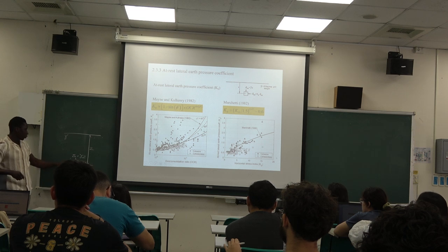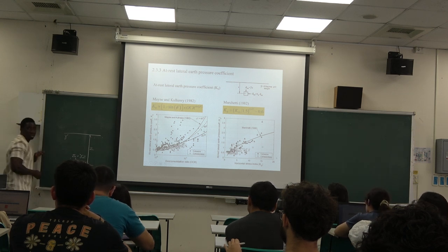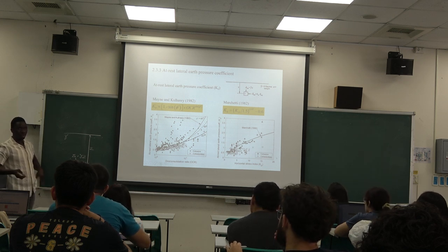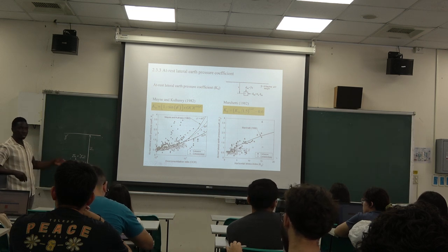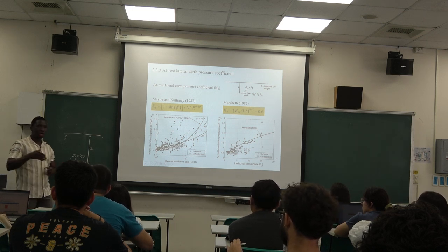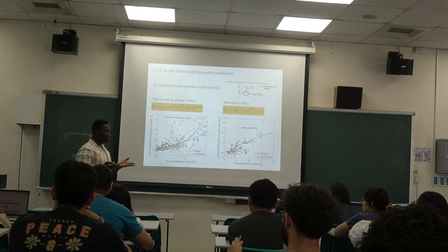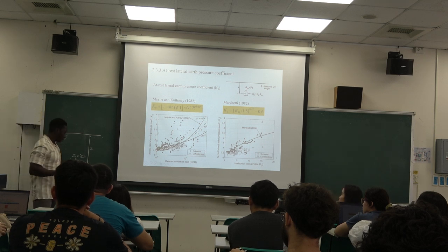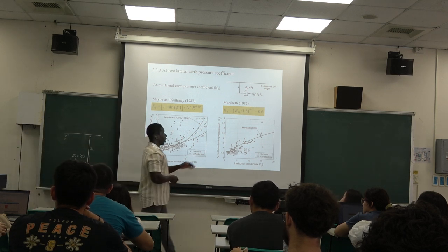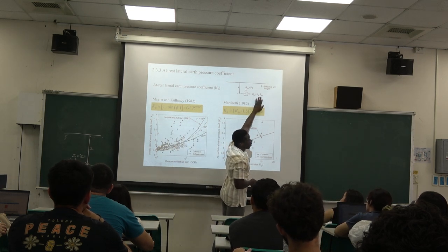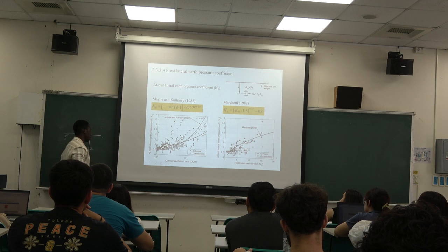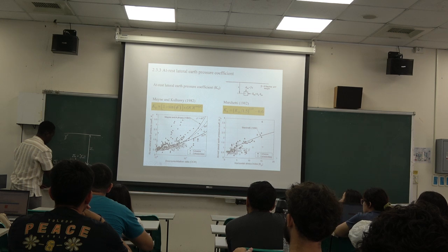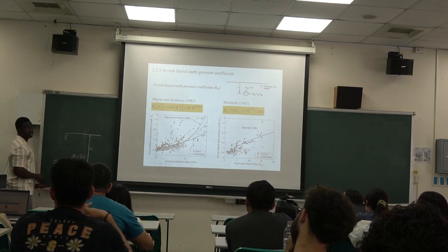But how do we calculate the horizontal stress that is acting along here? Because if we are going to design a foundation or an excavation, the horizontal force acting on our structure is also very, very important. Actually, most of our calculation is with regards to the horizontal component of the force. So we can calculate this horizontal force from the vertical component by just using the K0 coefficient, the at-rest lateral pressure coefficient. K naught sigma V.